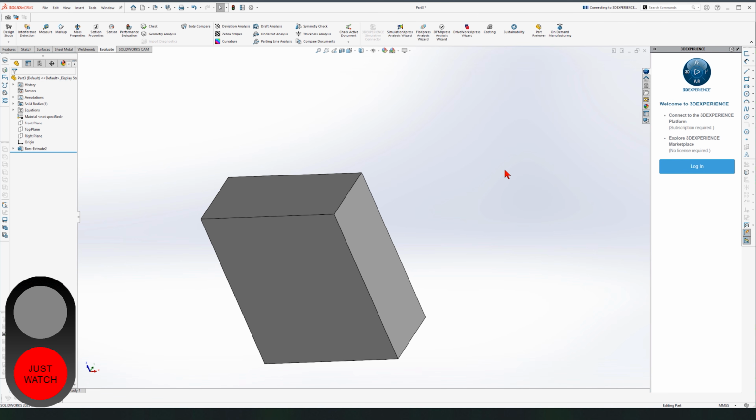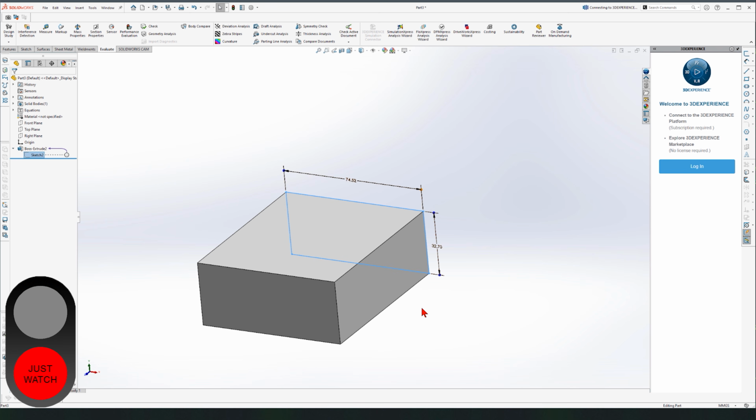Editing. Let's learn a little bit about editing too. We're not just creating, we are iterating all the time, right? So we are looking at our extrude number 2 on the design tree. We could click on this arrow next to it. Look at this. There is an arrow. If I click, it opens and it shows the sketch that we used with these values to create this. Now we want to change this value to 33.2. How do we do that? There are like 10 different ways we could do this. I'm just going to teach you one of them, the easy one. Not necessarily the fastest way, but the easy one to remember.